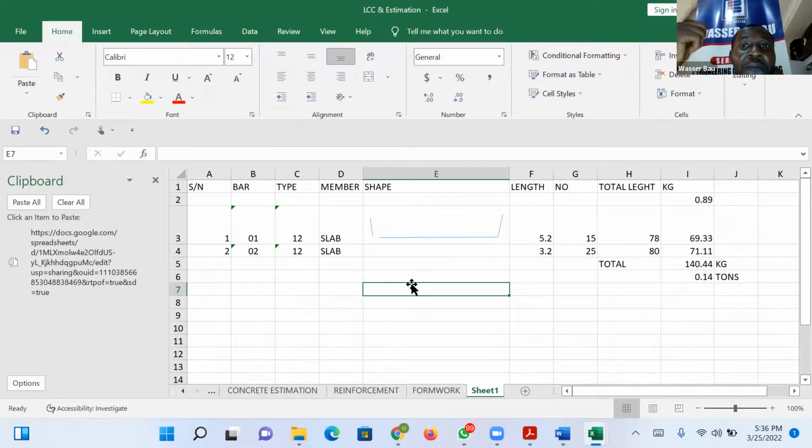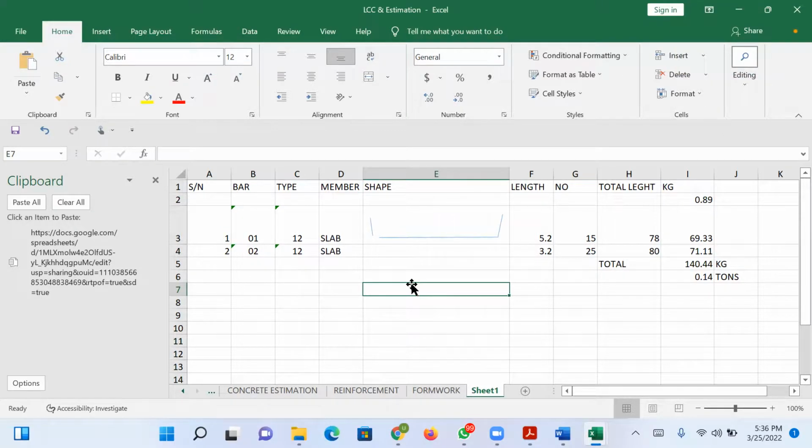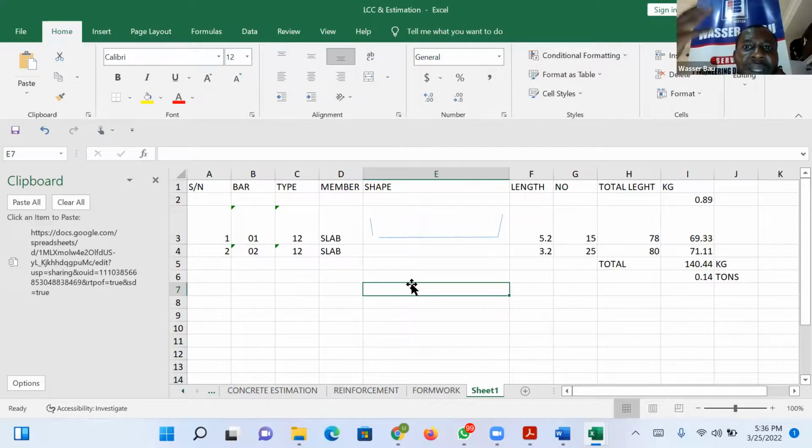And maybe it's only one floor. But when it's going towards 4, 5, 6 floors, 10 floors, then I'll use 100 kg per cubic meter. If it's not something that's being done in a very bad soil or is a raft foundation, then I can scale it up to say 150 or 120. But the standard is in BS code. But as a layman, if you want to work with laymen, you use the minimum number. You use your nominal reinforcements. Okay, this one will carry nominal reinforcements. 75 kg for every cubic meter, or 100 kg for every cubic meter.